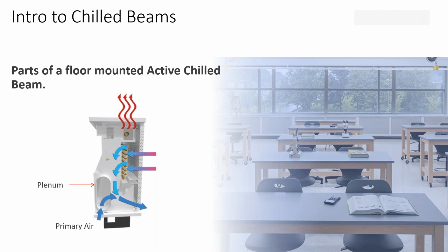You've got the sensible cooling component within the space itself. You're taking care of the loads based on a zone requirement. And in this case, we've got a fin tube heater, which you can either have heating options for, 4-pipe water coil, or a fin tube heater, which is what's shown here. And as we all know, that fin tube is a pretty effective way to heat through natural convection.